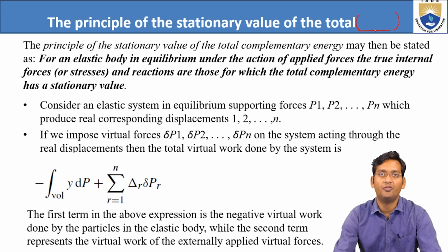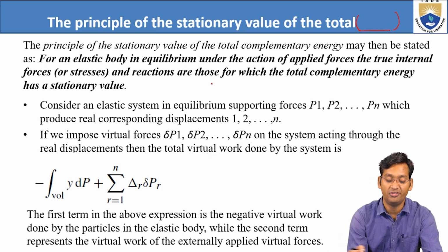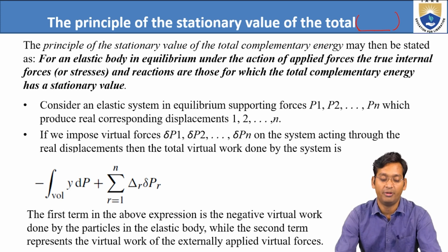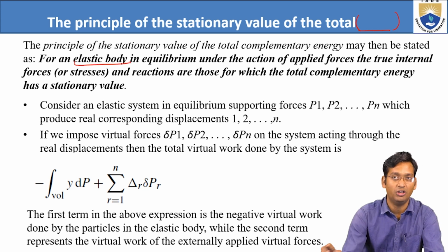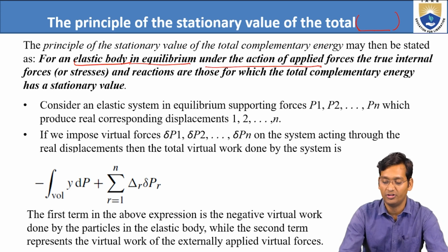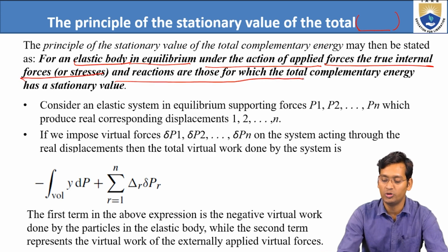The principle of the stationary value of the total complementary energy may then be stated as follows: for an elastic body in equilibrium under the action of applied forces, the true internal forces or stress and reactions are those for which the total complementary energy has a stationary value.